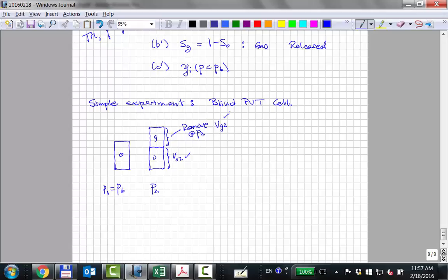And what happens is that when the last bubble of gas leaves the cell, that pressure gauge pops up, and then you shut the valve. So it's because of this compressibility effect. So you have to be quick, and you're doing the pump very slowly, but you're watching the manometer and moving it out, and then as soon as the manometer kicks, then you stop. So it's a visual thing.